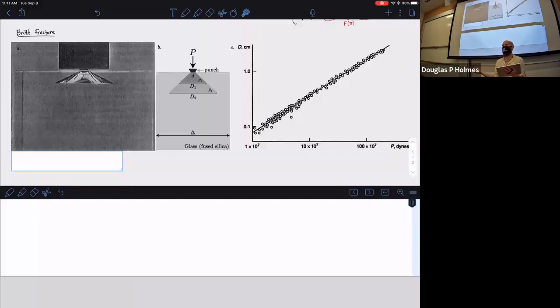So that seems to say the opposite: if I didn't see any plastic deformation, that suggests a linear elastic model should do pretty well. I haven't really had that large of strains. Strains are pretty small if the structure is able to go back together. So we should be able to learn something using a linear theory. And it turns out we can. We just have to think about how to account for the nonlinearity appropriately. So what's the nonlinearity in a fracture problem?